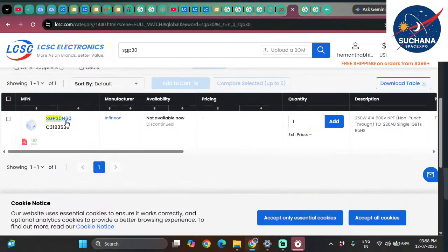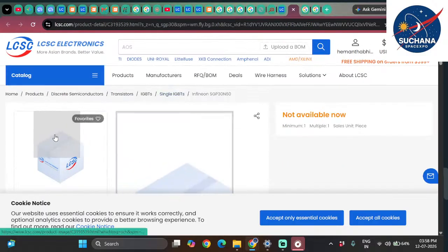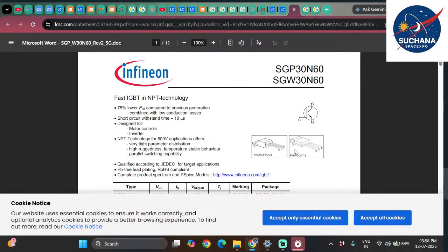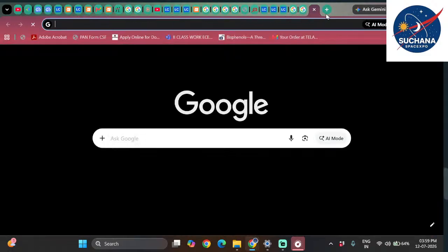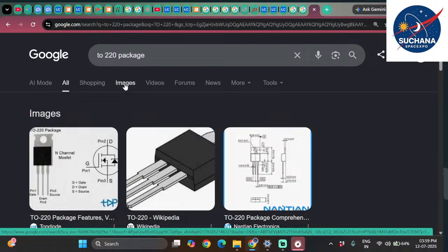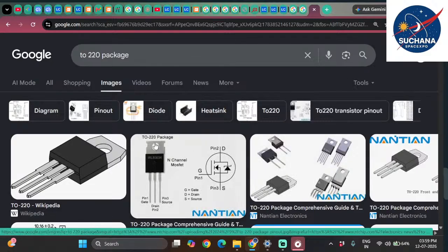You got something, but this is not actually the IC that we are looking for. It is some other component. If you just take the company name, it should be Sensirion, but here it is Infineon. Both are different. The entire packaging is also different. This is a TO220 package. You might have seen this kind of structure in transistors, N channel MOSFET and P channel MOSFET. Here we have one hole, which is used for connecting this package with a heat sink. So you can connect these TO220 packages with a heat sink as well.